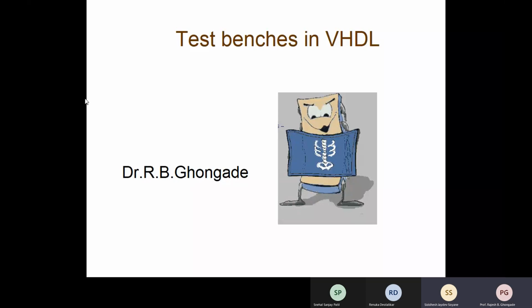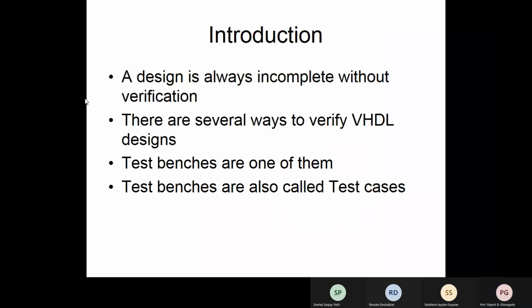So what exactly a test bench is, is what we are going to discuss for the remaining part of the lecture. A test bench is a very, very important concept. As I said, the HDL gives us the capability to even write the test bench for functional verification, even timing verification of your designs.